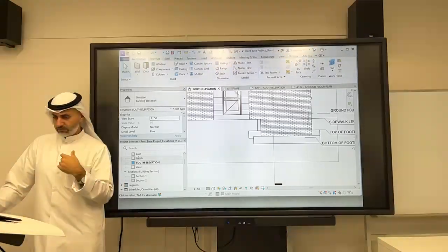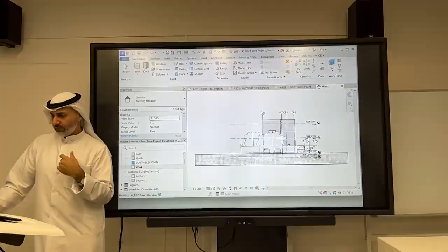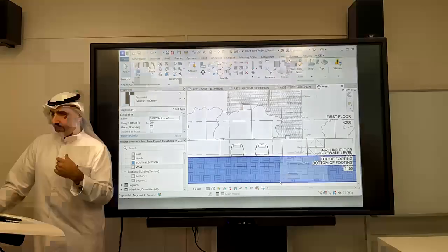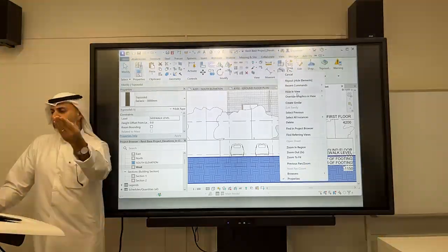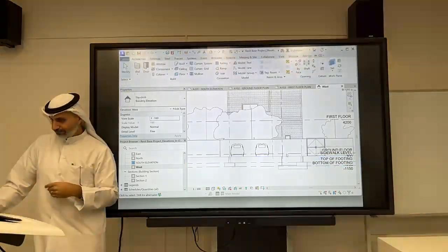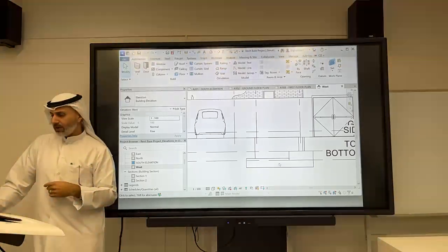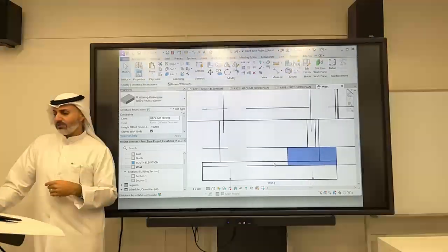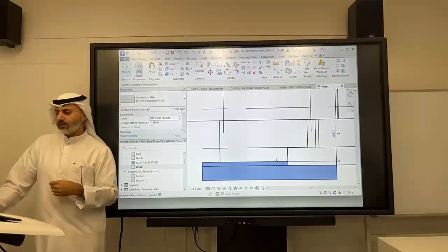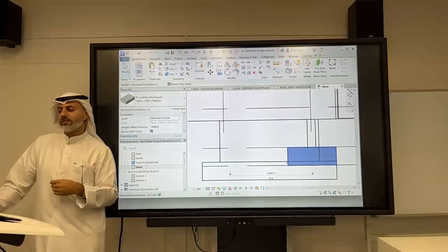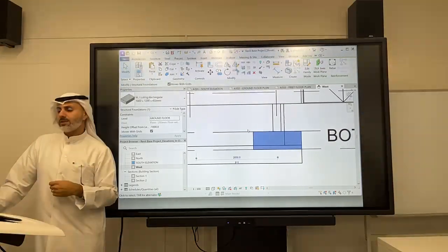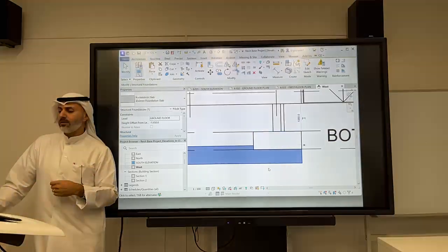If the other one is covering the elevator, you'll show the one that's covering it. Here, for example, this slab is coming in front of my elevator. So this gets the precedence. This gets priority and I draw this fully, and I don't show the full outline of these.